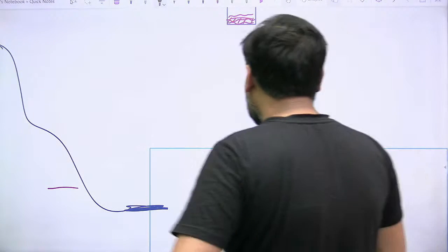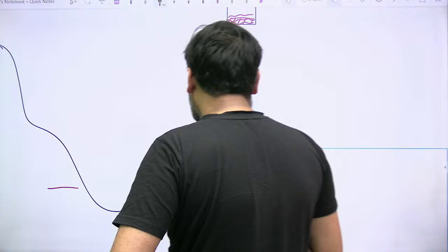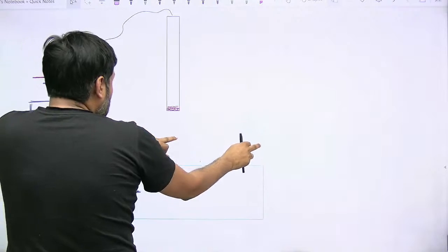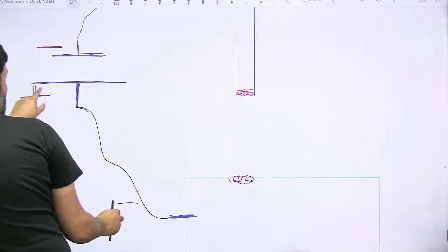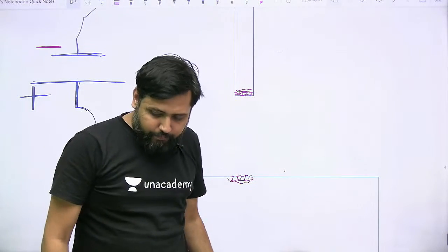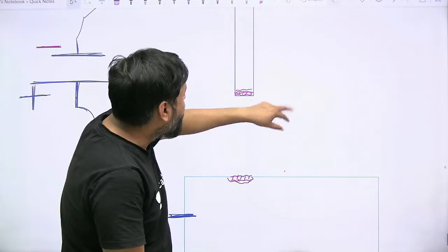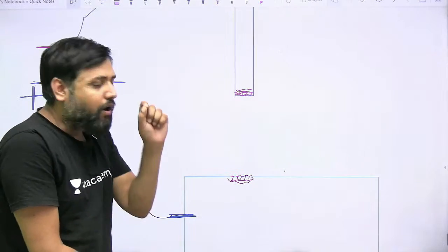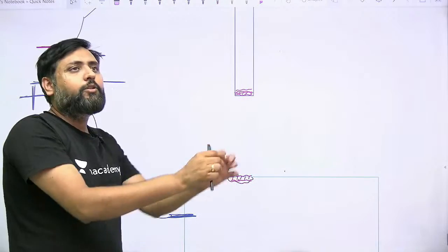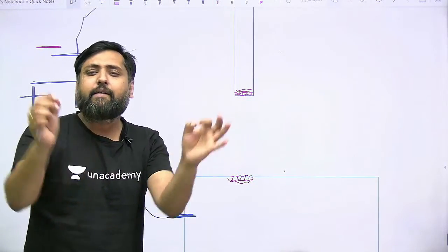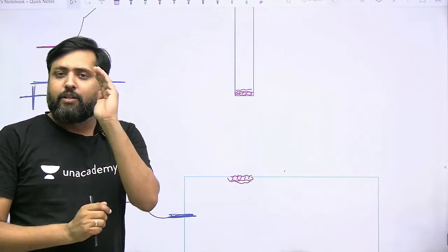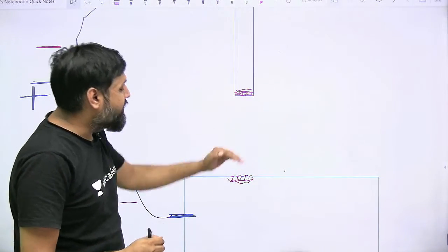So what happens, my dear? We have the two ends here. Yes, I had already shown you. The workpiece was positive, the electrode was negative. So as soon as the contact will be disengaged, both the electrode end and the workpiece end, which are severely heated, have a lot of unstable electrons and ions. So when the contact will be disengaged,